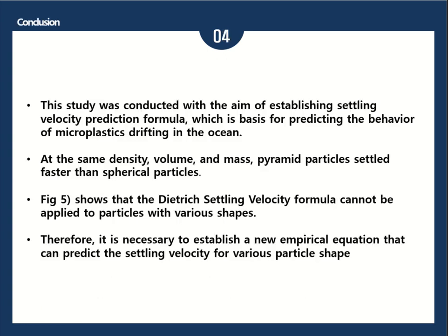So this is my conclusion. This study was conducted with the aim of establishing a settling velocity prediction formula, which is the basis for predicting the behavior of microplastics drifting in the ocean. At the same density, volume, and mass, pyramid particles settle faster than spherical particles. And Figure 5 shows that the Dietrich settling velocity formula cannot be applied to particles with various shapes.